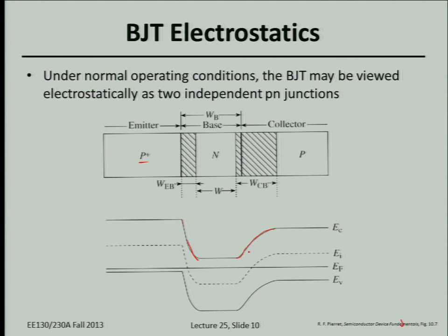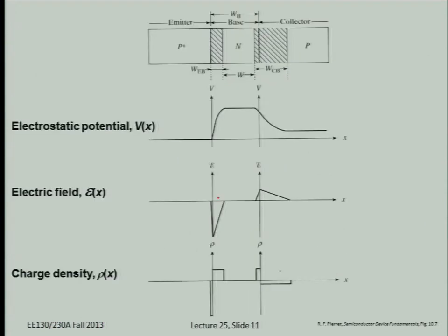Okay. All right. So basically, you could just draw a BJT energy band diagram like this. It's easiest to start with the equilibrium band diagram. So some definitions here: the quasi-neutral base width, we're just going to call W. That's an important design parameter for a BJT. And I think that's pretty much all you need to know. So in equilibrium,